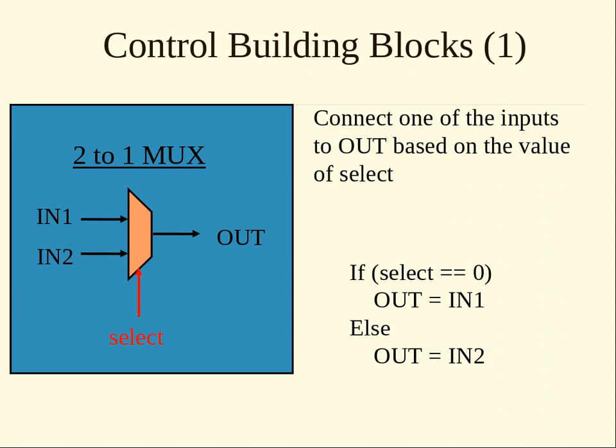Let's do this one. N1 is 0, S is 1, so that's another 0, 0, and 0 is of course 0. And then we have N2, which is 1, and regular S, which is 1, so the AND here is 1. 0 or 1 is of course 1, which is what we wanted. And this looks pretty familiar, and this will definitely be the mux.